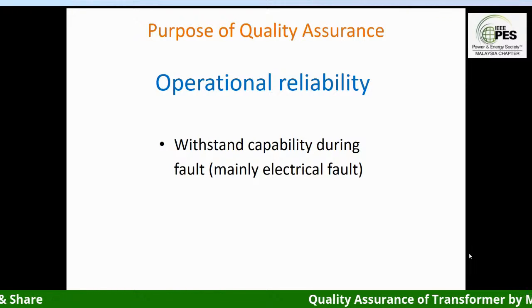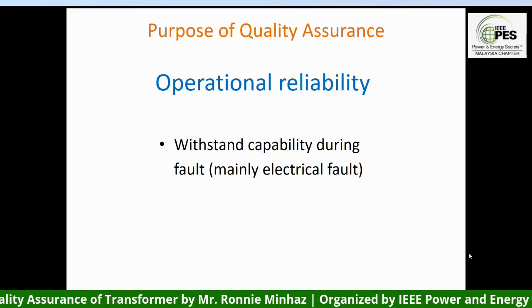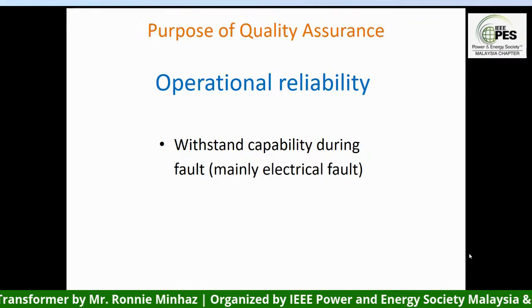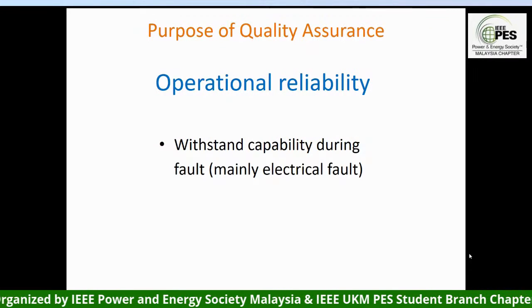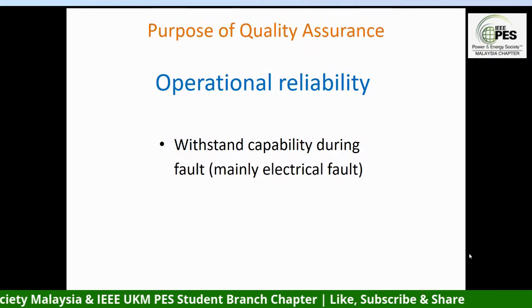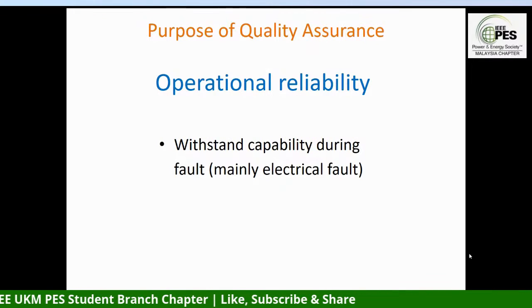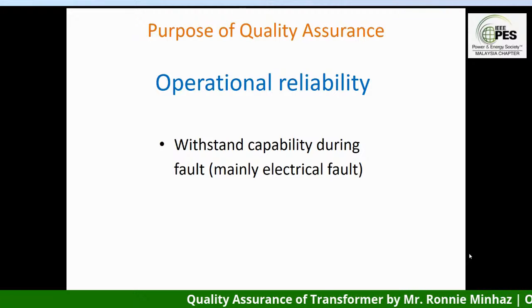One of the reasons is that, due to climate change and a few other reasons, there is a change in the climate, and the tree trimming process that they have in place is not coping with the growth of the trees. So trees are growing, for example, unusually due to the change in the climate, beyond what the tree trimming process handles, touching those lines and causing those through faults.